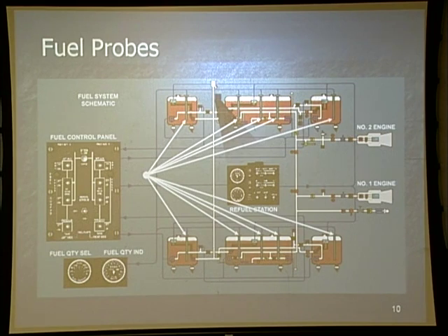Any questions about that? Now, the only other thing is the aux tanks feed the main tanks, which feed the engines and their associated systems. The right main tank feeds the heater, the left main tank feeds the APU. The aux fuel is only going to be transferred to the main tank. We cannot directly feed from the aux tanks to anything. Any questions about that? And we'll talk more about that here in just a second.